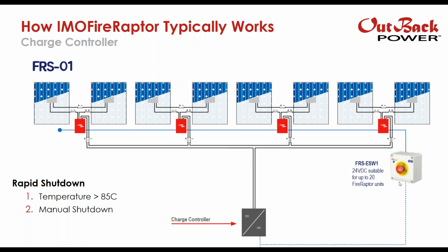But you also have a second choice with a battery-based system. You could also feed this by the inverter AC output. If that was the case, this would look a little different, and it's not shown here where this would connect. This shows a battery if you were to power this system with a battery. But if you were to power this with the AC output, then you would continue to use the AC to DC converter inside. Hopefully that wasn't too confusing. Essentially, you have options with a battery-based system: the battery, the AC output, or the backup panel. What this means is that a utility outage would not automatically initiate a rapid shutdown like you would see in a grid tie or string inverter.